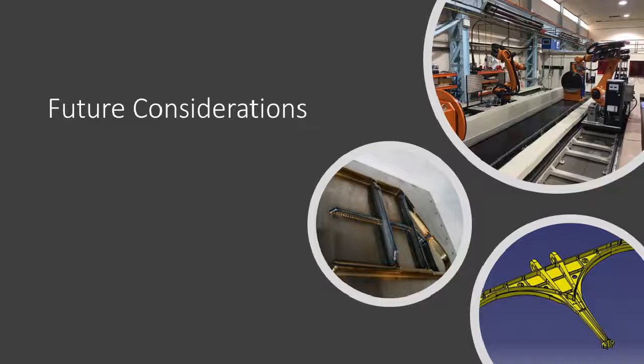And just following on from that, so that's post-processing after you've scanned it. Is there post-processing needed after you've manufactured the part using an ALM process? From the examples that we've seen, there is some finishing off of the component once it's come off the actual 3D printer, but these are just very small marginal finishes. There can also be, depending on which process you use, a requirement to use exposure to UV to finally set the polymer.